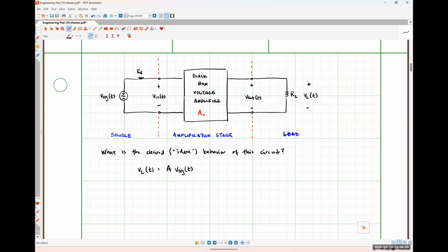So what I'm trying to lead you towards is all we would see would be some resistance, right? So our Thevenin equivalent circuit should be a voltage source in series with a resistance. If there is no excitation, all we're going to see is just that resistance, right? Our Thevenin equivalent circuit would literally just be a resistor in series with a short circuit because there's no Thevenin voltage to deal with, okay?